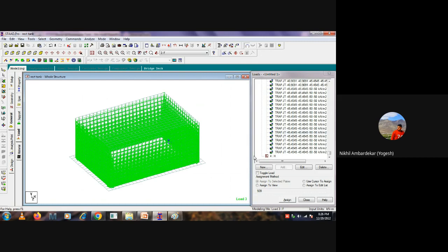Definitely you can create a plate any way you want, but if that axis is different, then you have to apply the load multiple times. In our case, we have 4 walls, so you have to apply this exercise 4 times: for the long wall, again for the second long wall, for the first short wall, and again for the second short wall. Understand what I want to say?